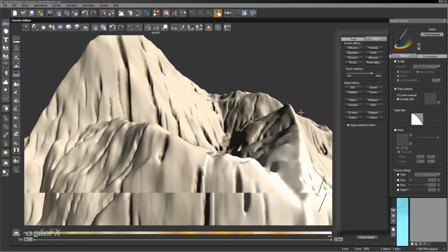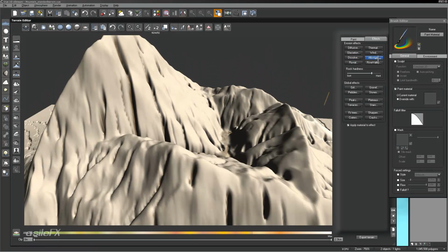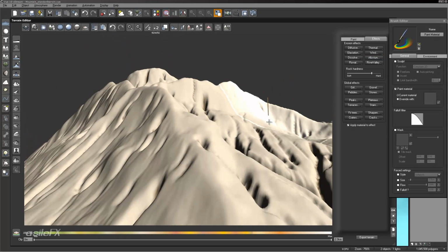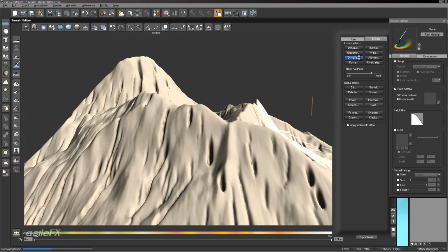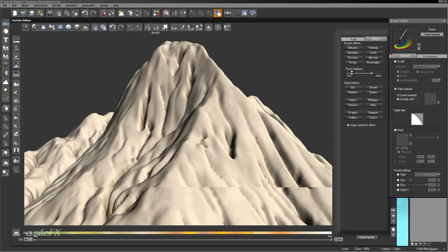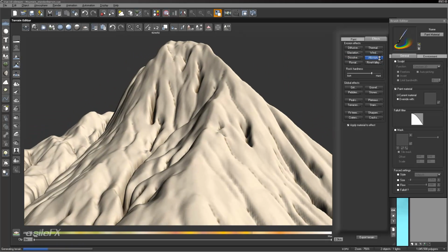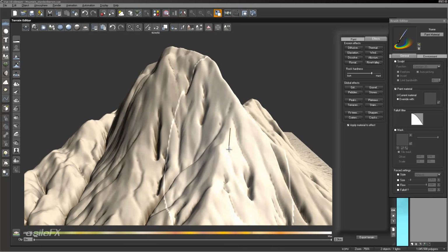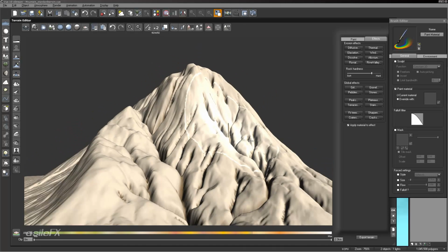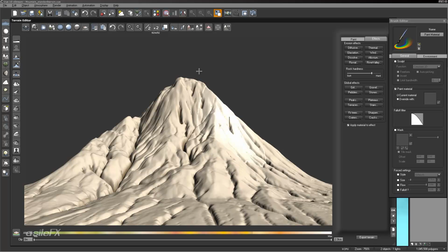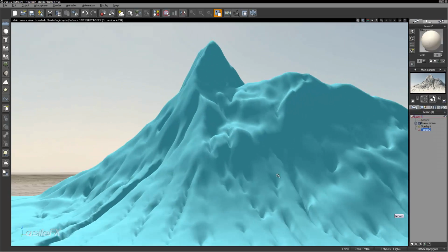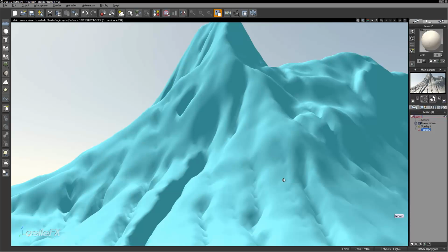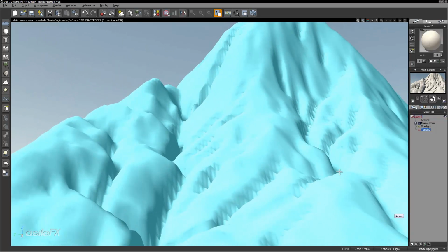It's a little hard to see. Material effects really end up being about half of the total effect. So you really have to apply it several times to get something really dark or really defined. That'll also depend on your resolution, because your material maps or the alphas that are being generated from painting, or in this case applying the effects, are going to be the same scale as the terrain scale and that terrain pixel resolution. So if you need more detail, you will need to increase the resolution of the terrain.